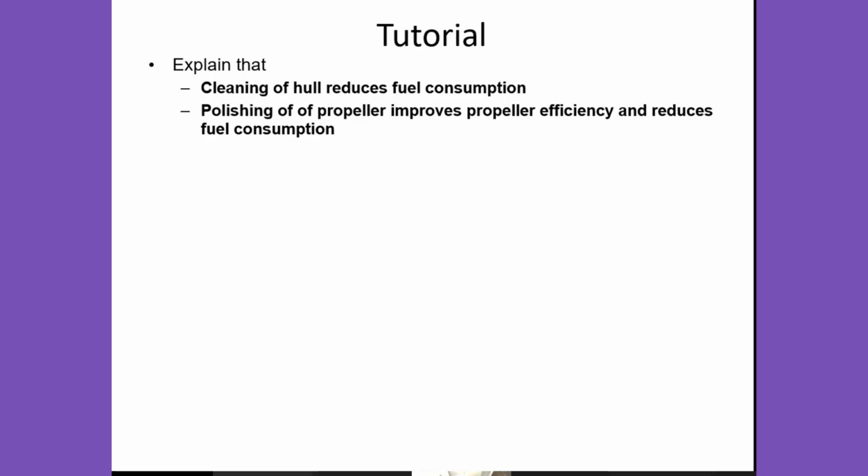That is why many times you find underwater cleaning or propeller polishing done to improve the efficiency of the propeller, to convert more of the delivered power, the power given to the propeller, into thrust power, which is dependent on the efficiency of the propeller.